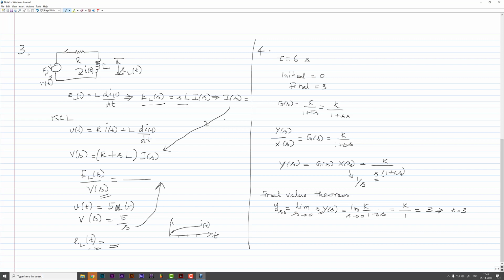So now you got the transfer function, Y of s you got here because the K value is known. Now you can take an inverse Laplace transform after taking the partial fraction for this and taking inverse Laplace transformation. Okay, so this is the transfer function you got by substituting the value of K.